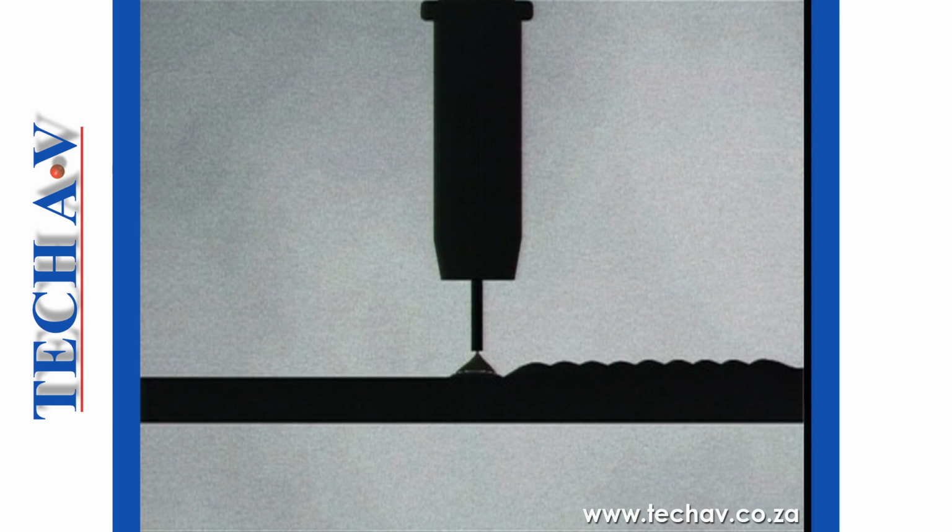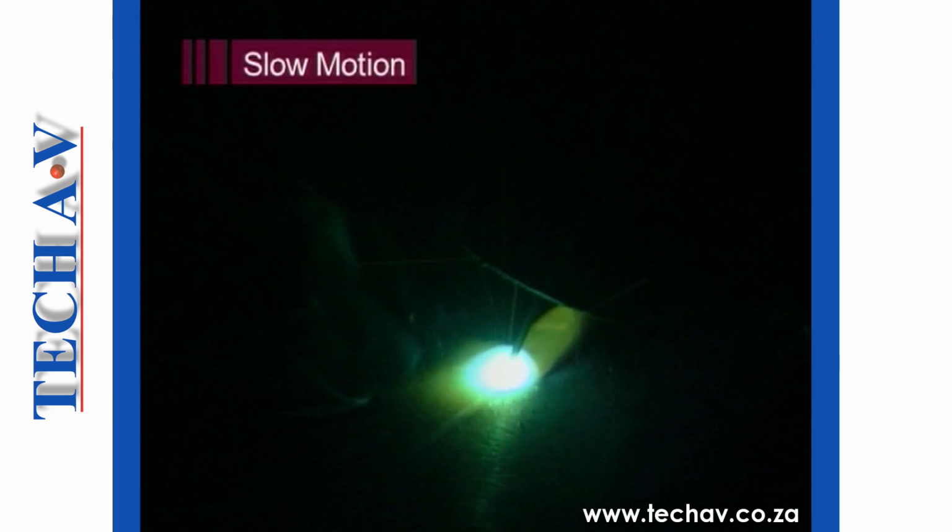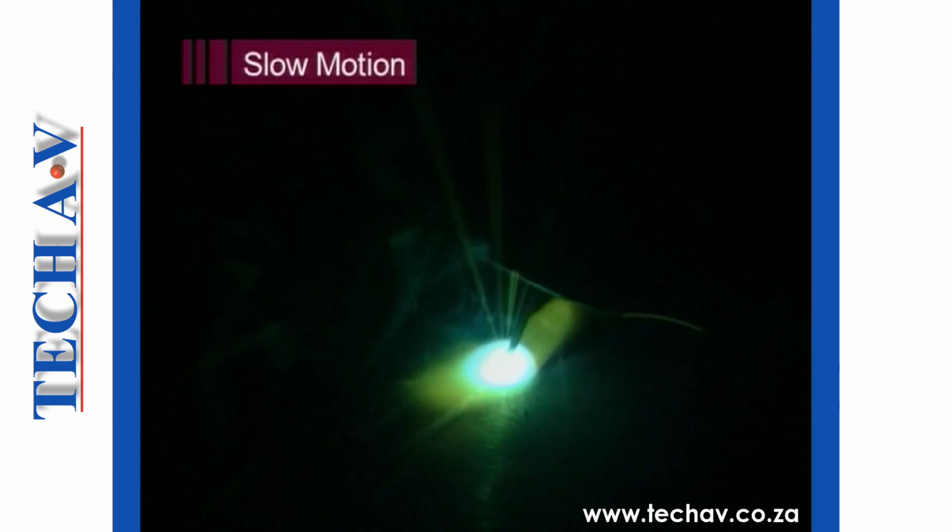The wire is fed continuously into the weld zone, and a cycle of arc on and arc off is set up at a frequency of between 80 and 200 times per second, which to the human eye appears as a continuous arc.